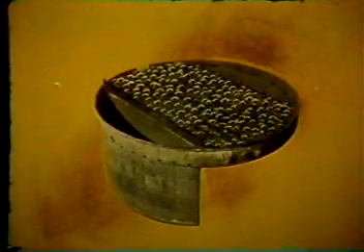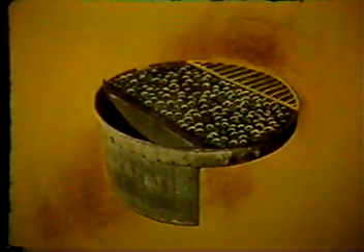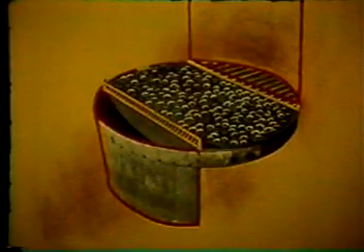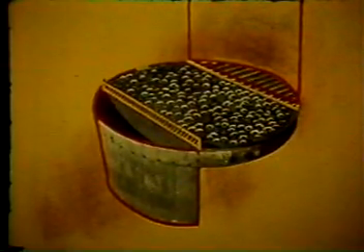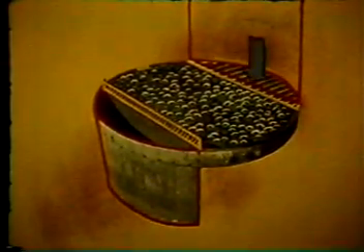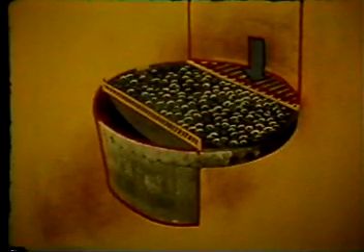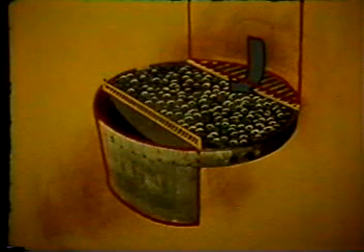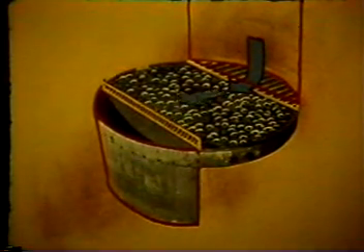A typical tray consists of the bubbling area, the downcomer seal area, and the downcomer area. The tray is usually equipped with an outlet weir on the downstream side of the bubbling area. Liquid descending from the tray above through the downcomer changes direction at the downcomer seal area and enters the bubbling area.